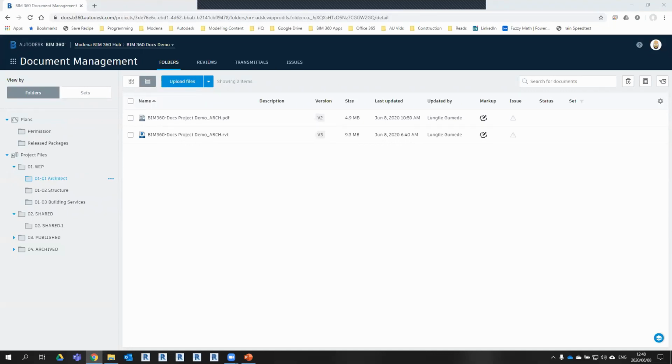Erika, are there suggested project file structures and best practice tool guidelines? Yes, there are, Erika. If you go look at the ISO standard or the PAS 1192, they do highlight to a degree what is the recommended process of building a platform for this. However, we have found that various companies have various methods of doing it. So it's really project to project, team to team, how you want to navigate through this, and the complexity of the project might become a big factor. Part of this is also the different BIM platforms that are enabled on a project that might dictate how the folder structure should look.